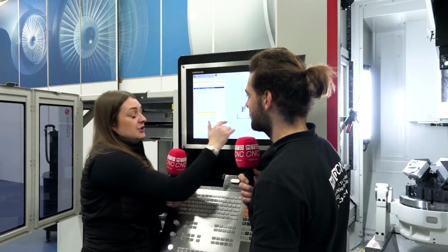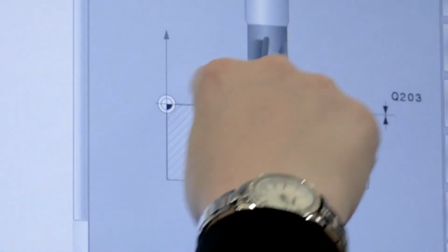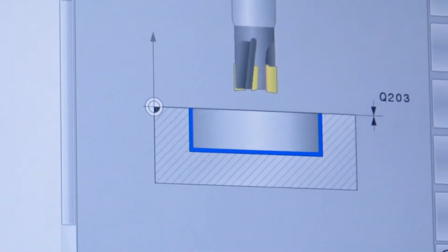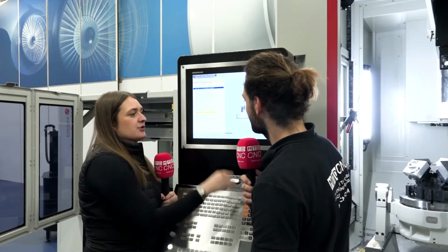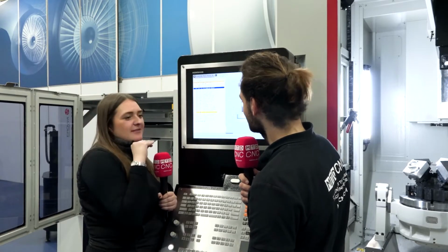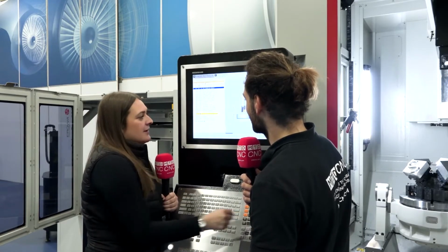Okay. Surface coordinate. So where are we starting? If you've got a bit of material that's got a ruggedy edge on the top, we haven't face milled it at the minute. Yours might be 2.5 mil over. So if it is, we can put 2.5 in. But for instance, we'll say it's all flush, so it's 0. We're all set flat. Okay.